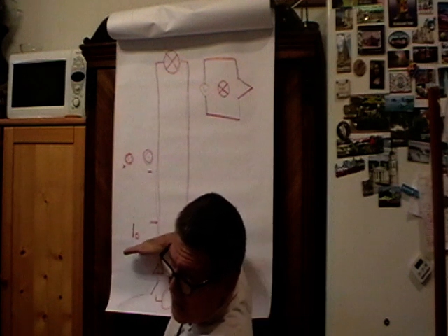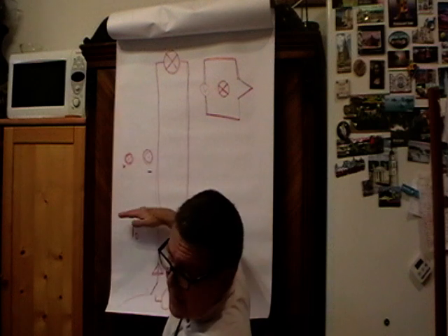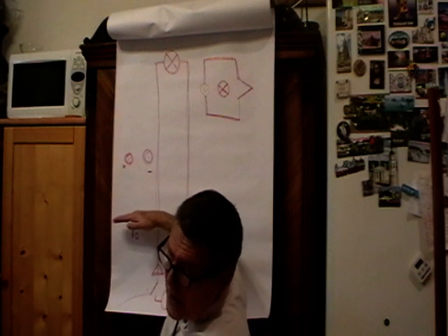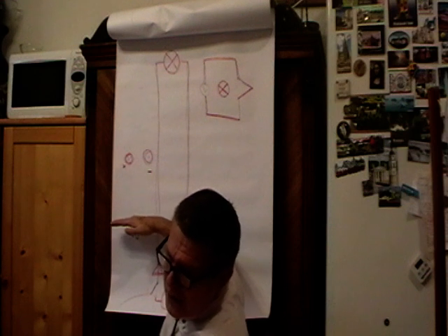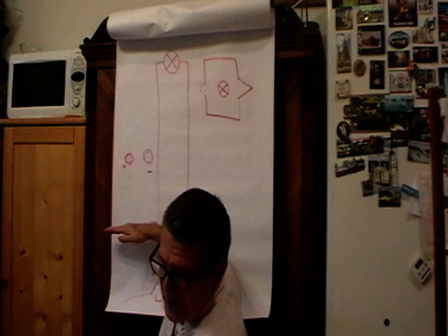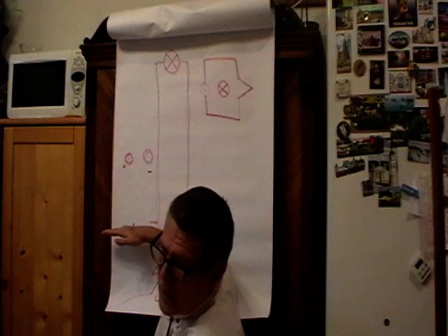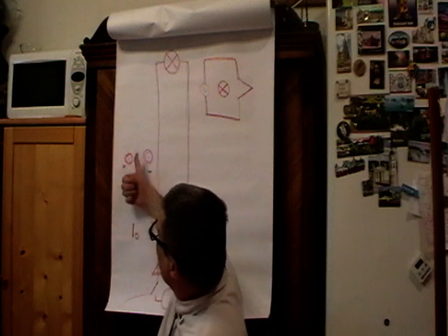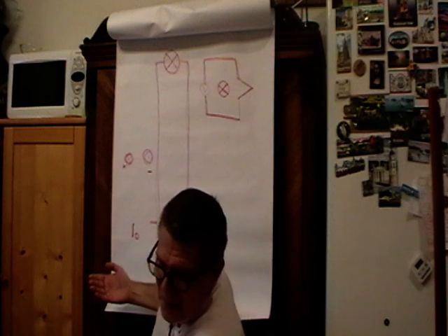And at those points where this wave propagating upstairs again reaches, we have again voltage. But to achieve that voltage, we have to provide extra current. We have to provide extra I0. But already we have two I0s flowing up in this conductor, and we have to provide a new I0 to get the voltage back.